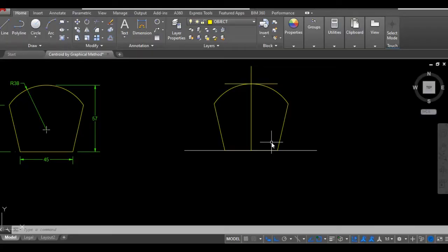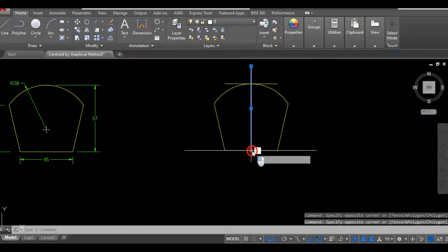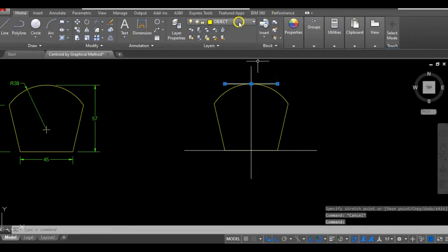Now, because of that fact, when we're doing this question, we don't need to replicate both sides. We just need to do one side, and then now we're using AutoCAD, so we use the convenience of AutoCAD, and we could just copy and put it on the next side, and voila, we're done. So that's a plus of AutoCAD. If we're doing this by hand, you would know the struggles. So this line now will represent our X. I'm going to put this in the 0 layer, and my 0 layer represents construction lines.